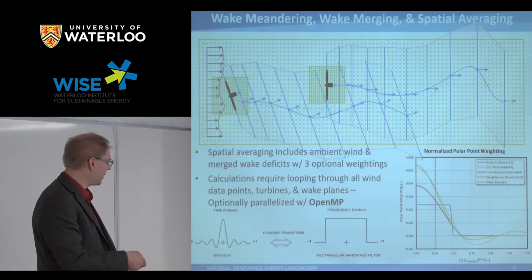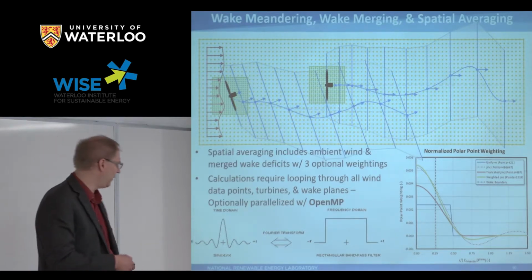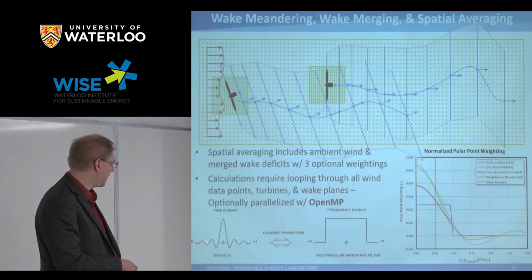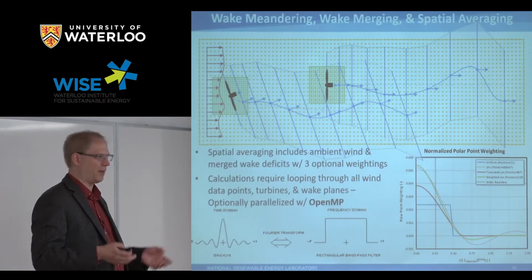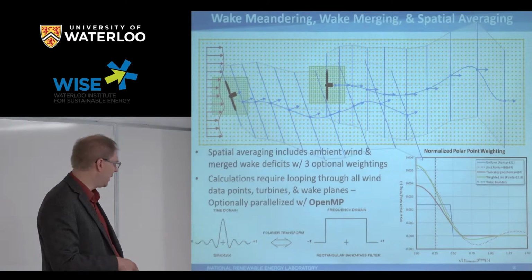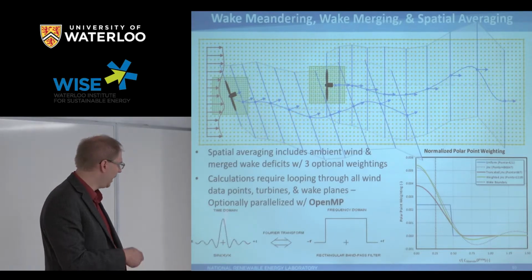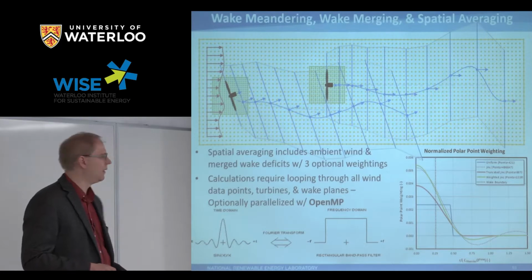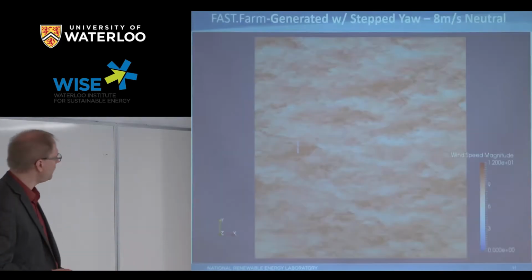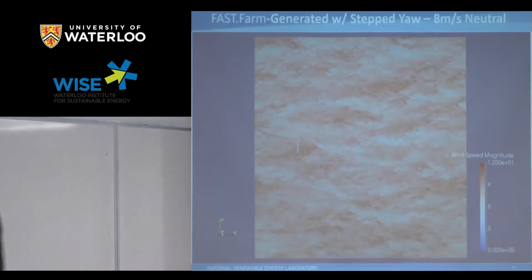So what we did is we said, let's flip this thing around, essentially. If I spatially filter with this weighting here, then in the frequency domain, I'll get a nice idealized low-pass filter, which is what I really want my wakes to meander around. So that's what we do, is we allow the user to basically apply weightings based on what's called a Jinc function in a two-dimensional plane, and then we get the proper filtering we want in the frequency domain. This is showing an animation of what this thing looks like.